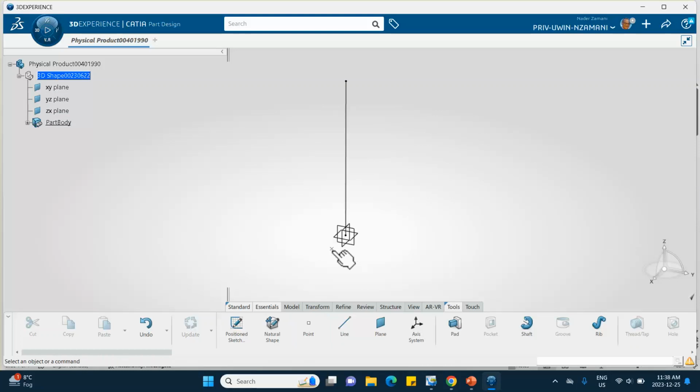So there is a point here which will be used to orient the cross section, because remember, if this is a circle, it doesn't matter. But if it's an I-beam or a rectangular section, then it does matter how it's oriented. The cross section is still the same, but orientation is important. Okay, let's leave it like this.